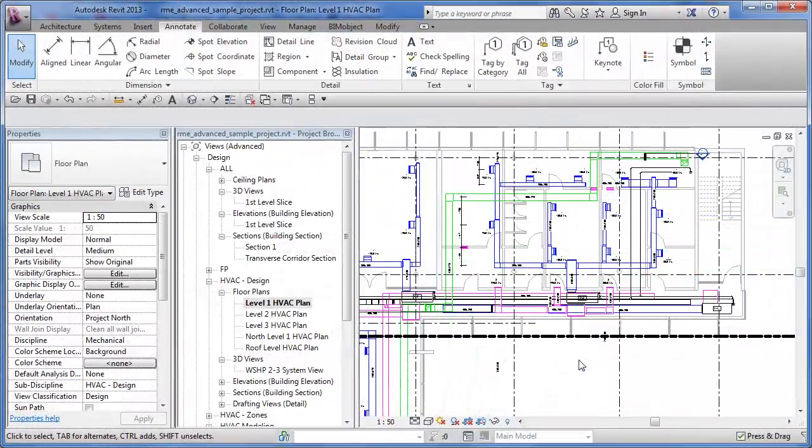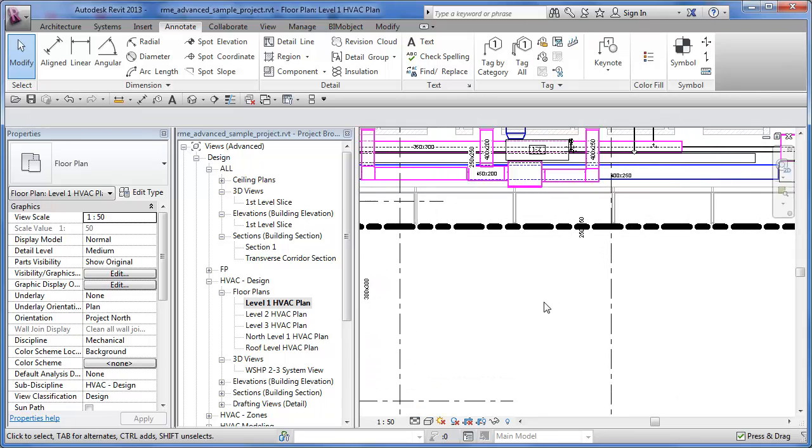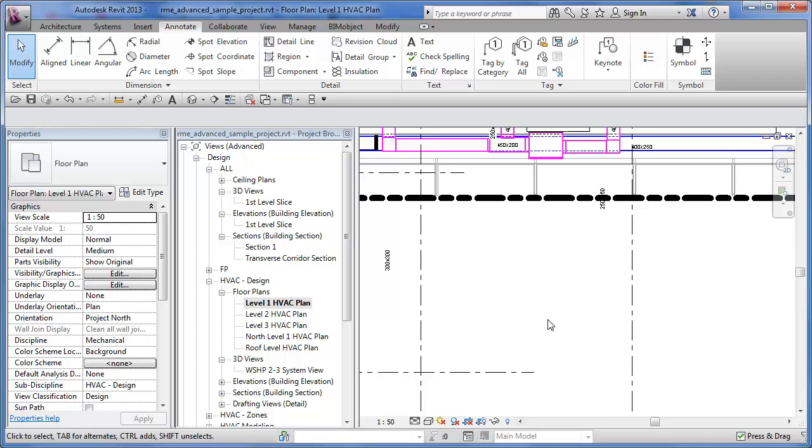And our next little enhancement with our 2013 Revit is the diameter dimension with a nice little diameter symbol in there as an option. So I'm just going to zoom in here. We could draw some walls in a circle, or a sketch line, or a dimension line, or a detail line, or anything that's really circular that we want to get a diameter off of.